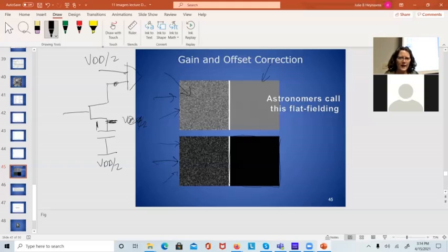And we found, on average, it takes about 5 seconds of power down time before the 1s start decaying to 0s. Each individual cell has a decay time associated with it.